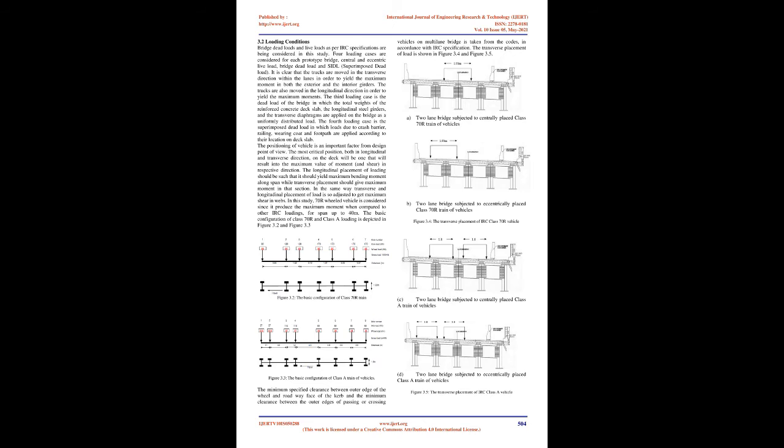25. AASHTO LRFD, 2010. The current AASHTO LRFD bridge design specifications, AASHTO LRFD, 2010, recognize that the LDF is a function of girder spacing, span length, slab thickness, and beam stiffness, and so they introduced a new LDF equation, based on elastic finite element analysis, FEA. The LDFs are specified differently for exterior and interior girders, for shear and moment, and for one lane loaded and two or more lanes loaded cases. AASHTO LRFD specifications introduce a reduction factor for LDF as a function of skew angle.